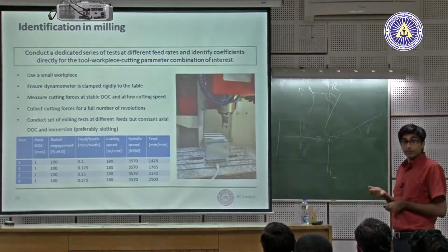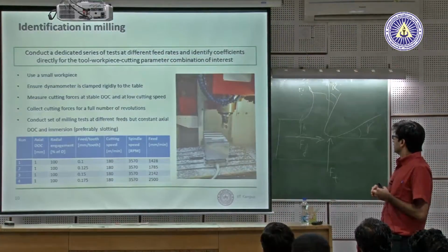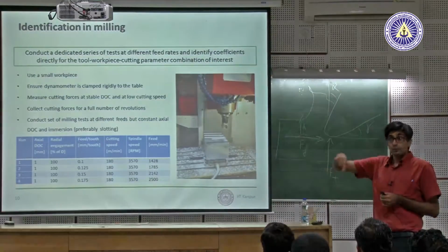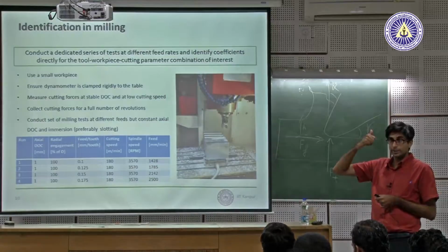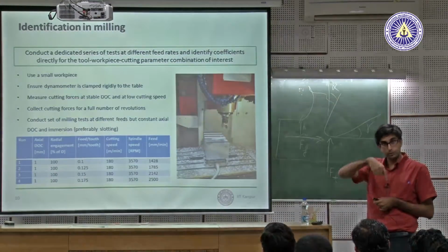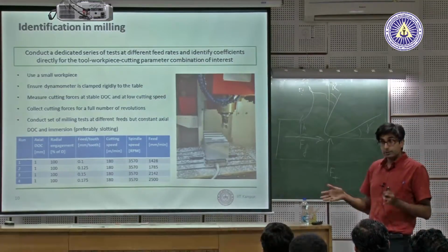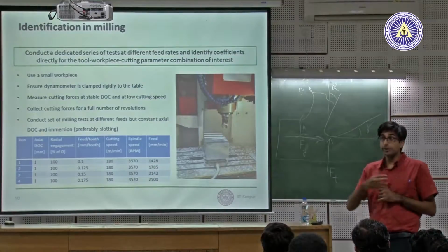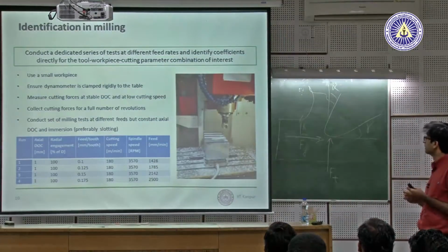When you're collecting information, so signal processing or gathering data, make sure you do it for at least a few complete revolutions of the cutter. Because if you saw yesterday, forces are periodic as a function of time, as a function of tooth angle. And we will average these forces, so make sure you have it over several revolutions, so you have good data. Very important.